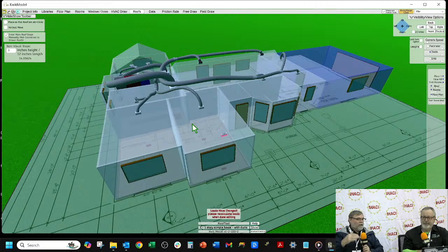And then the cost comes down on the price of the equipment, and the cost to run it comes down because it's smaller. And they're more comfortable too. I found oversized equipment causes more comfort problems than undersized equipment.